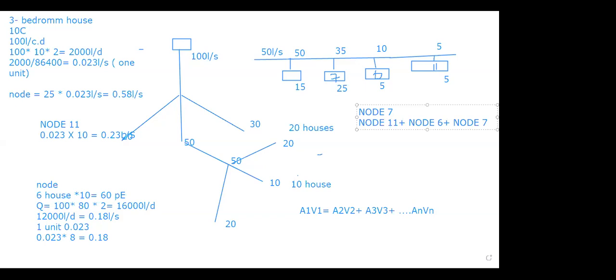But when you say we need this to feed our Epanet system, I was thinking Epanet is designed in a way that we can feed only, maybe, the number of houses for each node, and then it does the adding of downstream nodes automatically. We don't need to worry about it. But it looks like this is not the case.